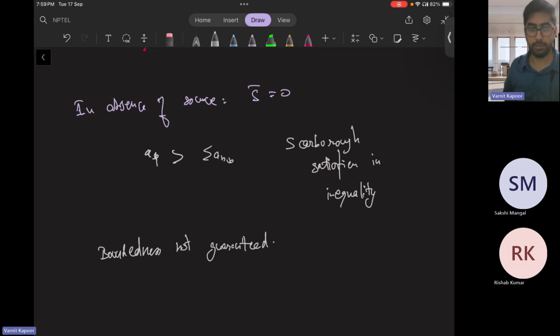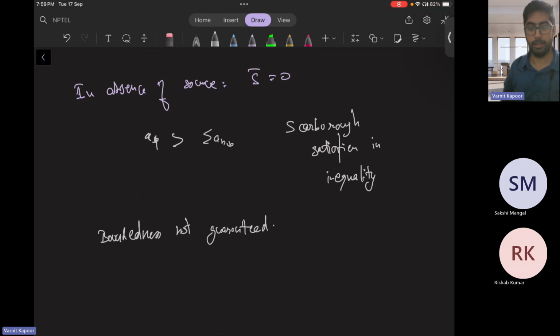And you can extend all this: if you have gamma which is not constant, you can interpolate. You can extend to unsteady. So you can have linear source terms, linearization of the source term. You can go with the under relaxation. You can do the stability analysis. You can deal with Neumann boundary condition, mixed kind of boundary condition, and so on.